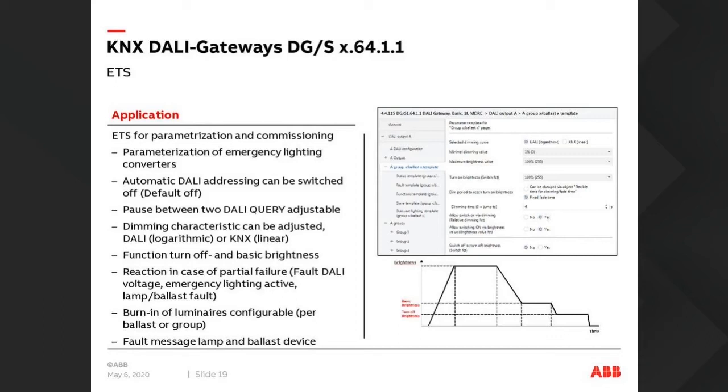And what we found in a few instances was that at the standard time, sometimes there were issues and there were problems. Again, this was probably down to the DALI ballast manufacturer. But what we are able to do now is slow down those queries so we get fewer errors when we're communicating on the DALI bus.